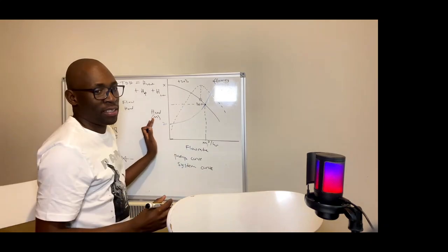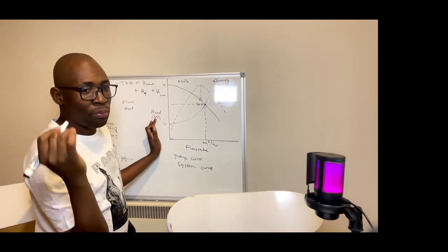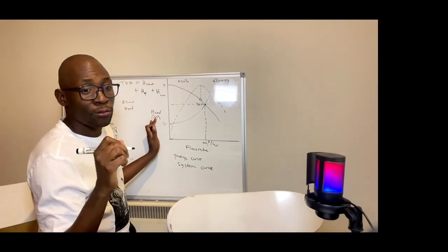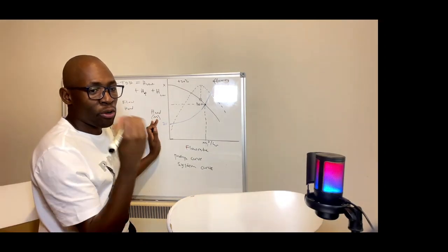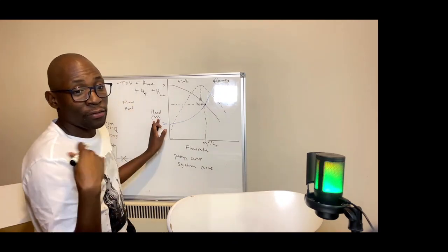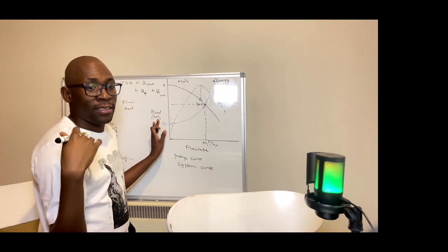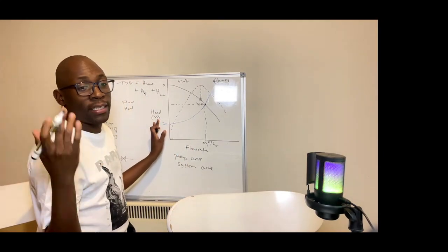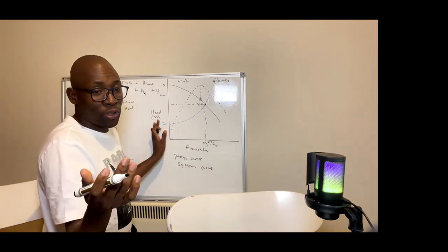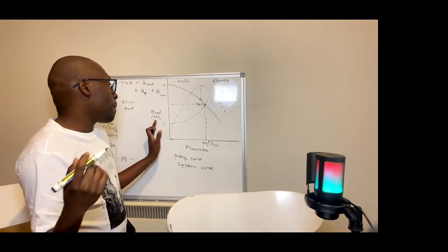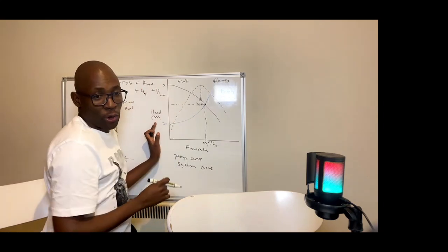As you are selecting your pump, make sure that your duty point is close enough to your best efficiency point, because if it is far away, it means the pump that you've selected is not efficient, and this might result in more OPEX cost, and your pump might not last as long as it is supposed to. So you need to be aware of this.